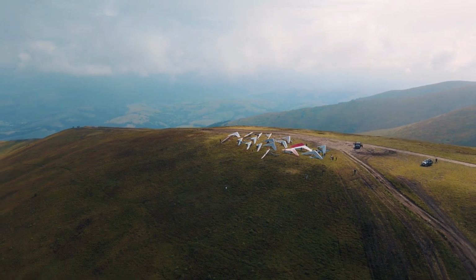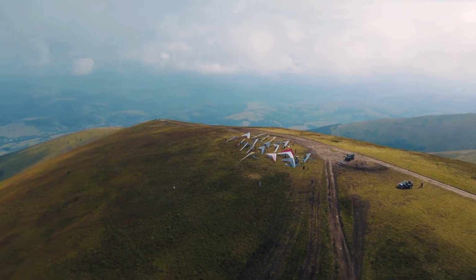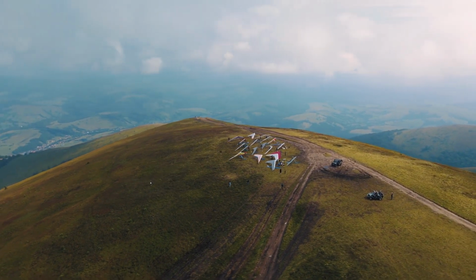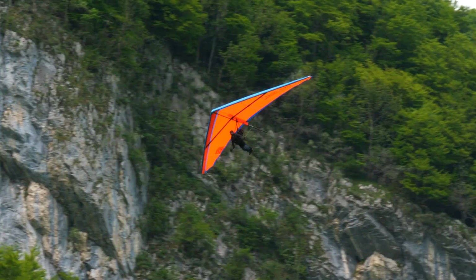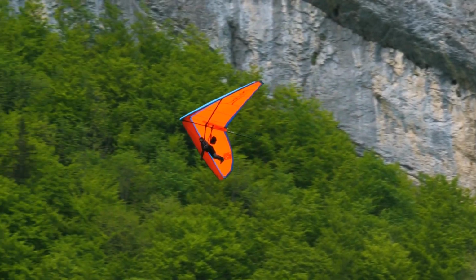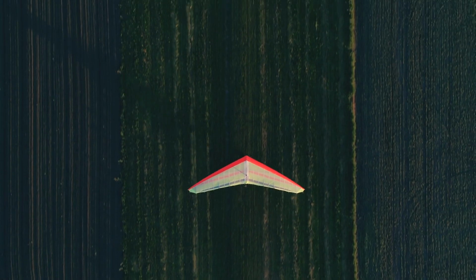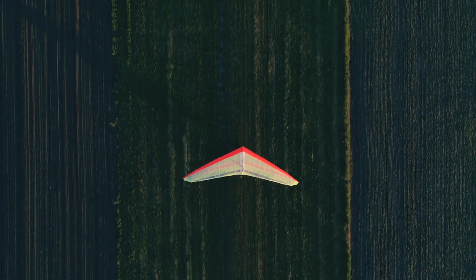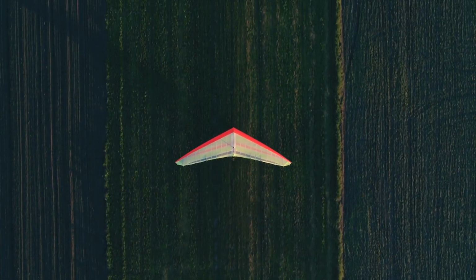Now, let's gaze upon the WSC wing from above. At the center is the wing root, and at each end, the wingtip. Wing chord refers to any section of the wing parallel to the wing root. The wingtip chord is where the trailing edge extends furthest rearward, a dynamic feature depending on the specific wing design. The nose angle is the angle formed by the leading edges, typically ranging from 120 degrees to 130 degrees.